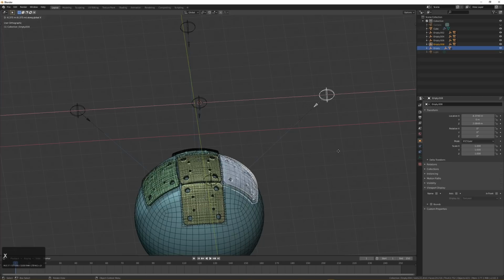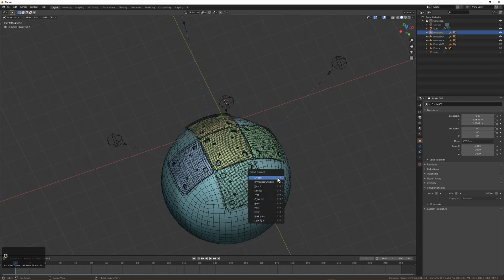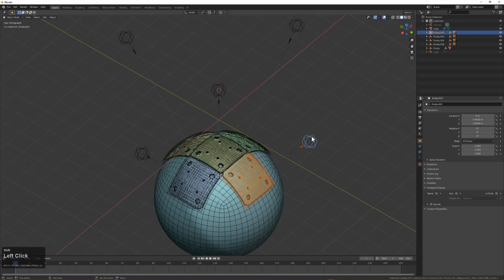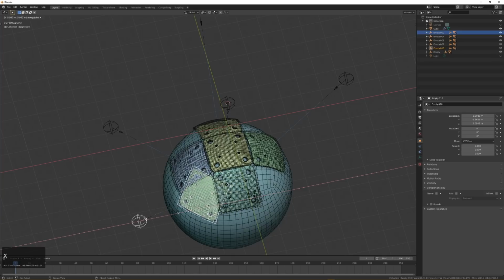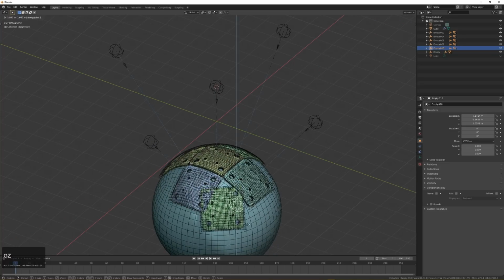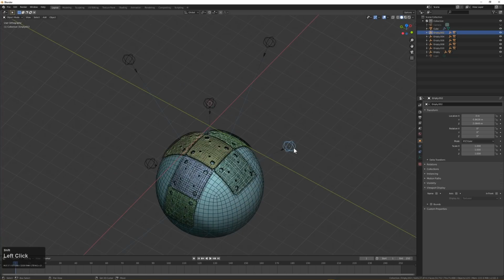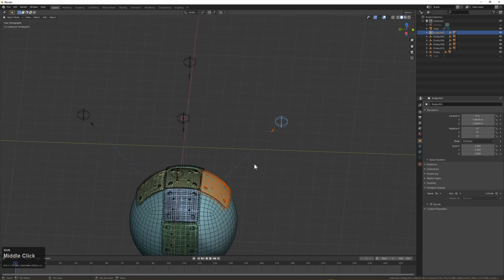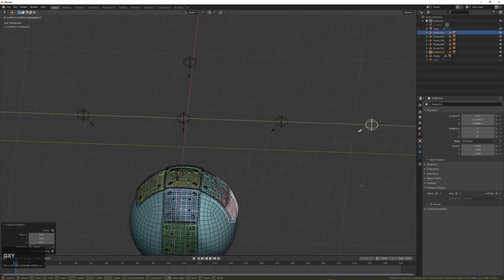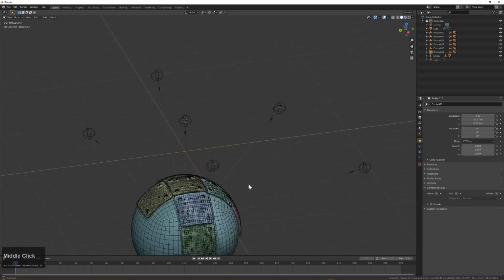And this is just one way you can deal with curving ngon meshes in particular. I know it can be a little tricky dealing with curvature and ngons, and there's a large contingent of people who are quite against ngons out there. So I do want to show some friendly ways of working with them and getting effective results over the course of this, because I feel they get a bad rap, and there's definitely a reason they exist in 3D. It's definitely there for modeling purposes.